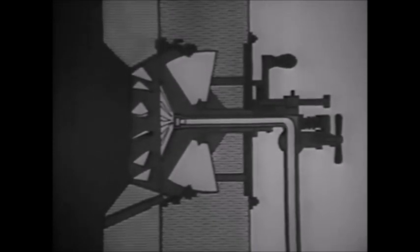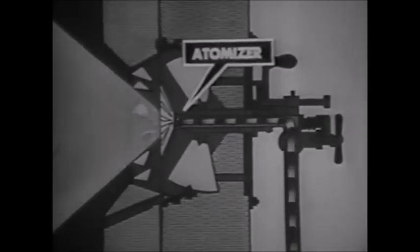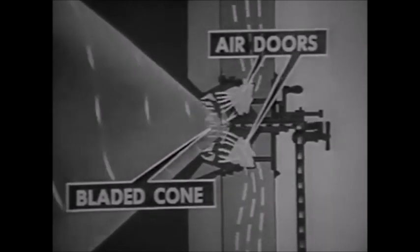Burners in a boiler provide the combustible mixture of air and fuel oil that is burned in the boiler furnace. As seen in this view of a typical burner mounted in a furnace wall, the burner's atomizer reduces the fuel oil to finely divided mist-like particles. That is, it atomizes the fuel oil. Then the air doors and the bladed cone in the burner register mix these particles with air to form the